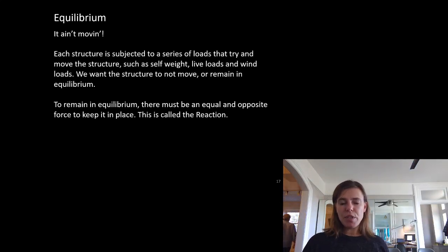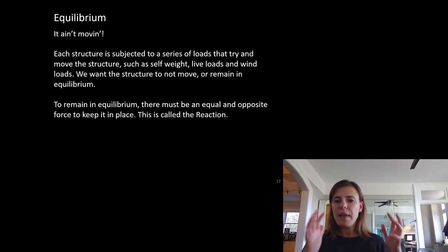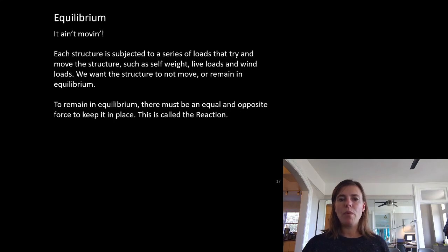So everything is subjected to a series of loads. So self-weight, live loads, wind loads, anything. We want the structure not to move or remain in equilibrium. For it to remain in equilibrium, there has to be an equal and opposite force keeping it in place. That would be our reaction.